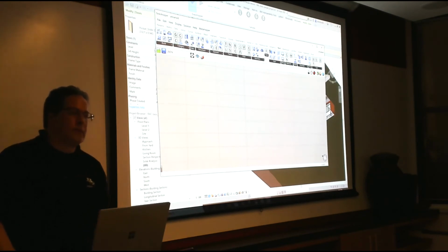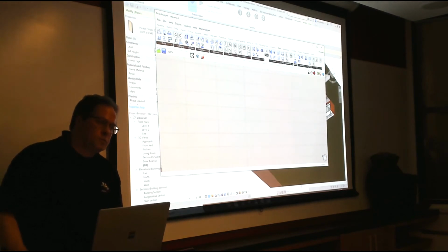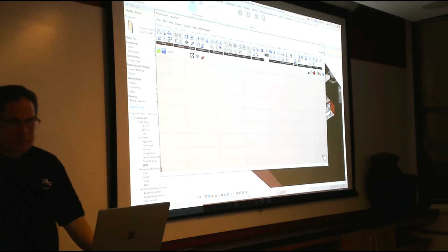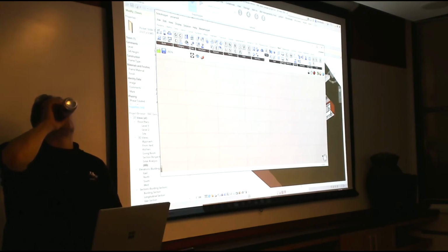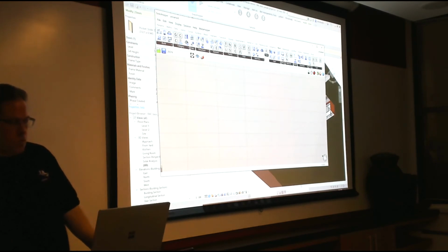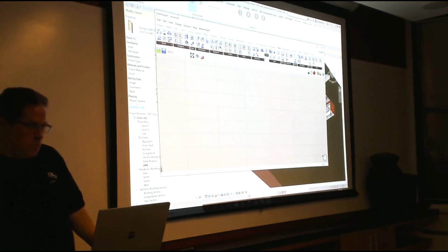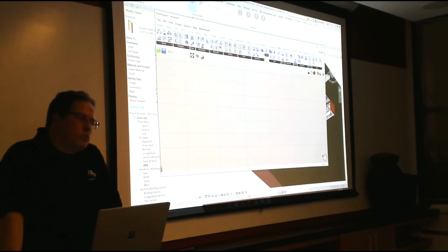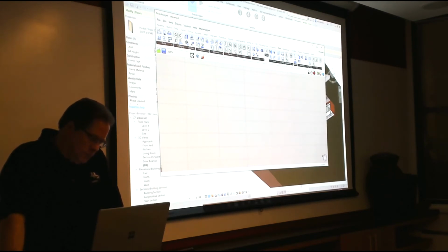Yeah. So I have found a weird limitation in regards to family redefinition within Rhino and then pushing out an adaptive component using those families. I'm trying to figure out a way to close the loop between defining geometry within Rhino, then using that defining geometry within Rhino to push out to an adaptive component family in Revit, and then tying it back into Rhino as points so that the adaptive component family can adhere to.